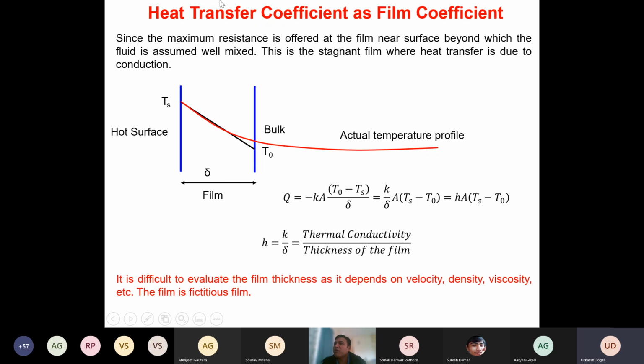Okay, all right. So what I'm trying to say is most of this resistance is taking place over this entire length up to this. But since this is the dominant part, it's a realistic assumption that all this temperature difference is taking place only in this small film. Can you see why we are making this assumption? Of course, there is some change here towards the end, but we are neglecting that because that change is small with respect to this entire change we are looking at, isn't it? All right. So it's a realistic assumption that most of the temperature change is taking place only in this film.